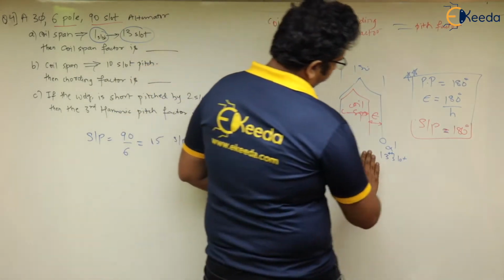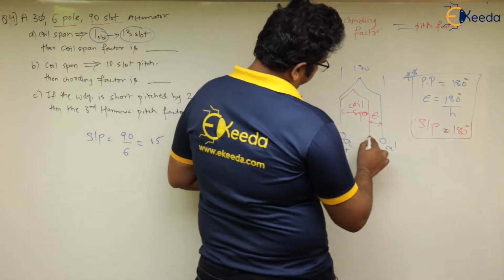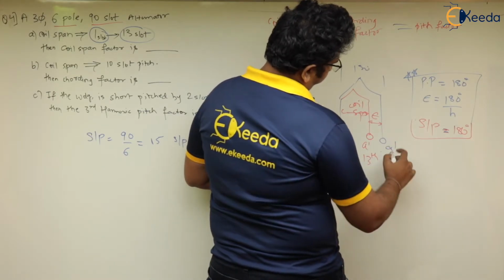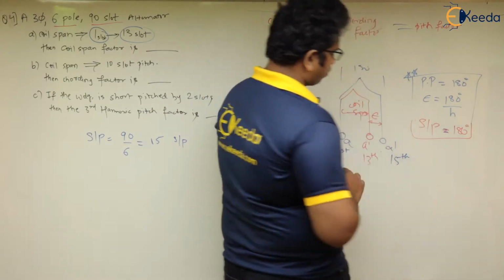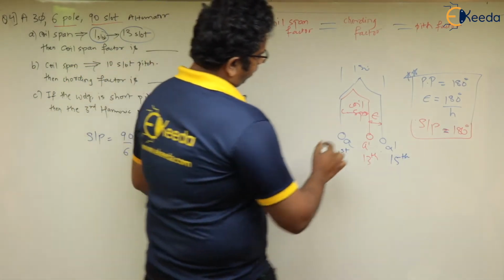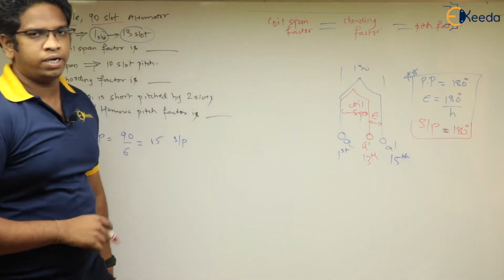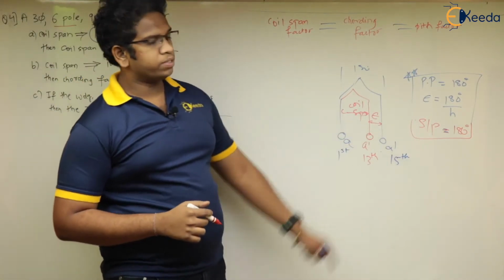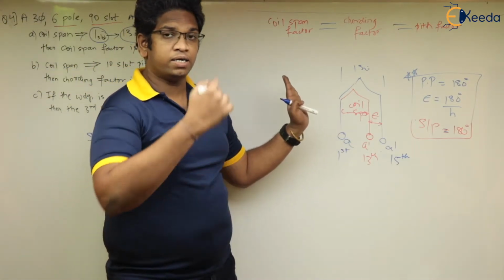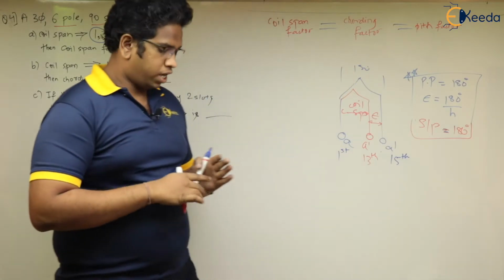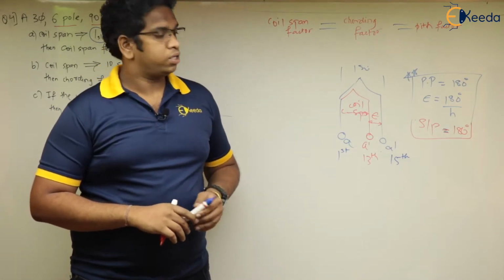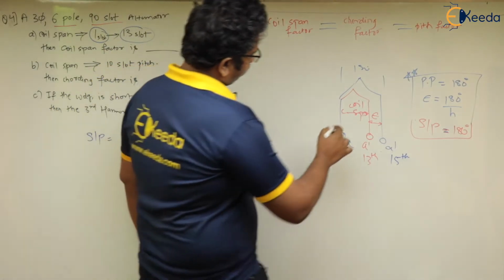Which means that this is not in the 15th slot. A dash is right now in the 13th slot, and our 15th slot is this one. Getting my point, right? Our 15th slot is this one. Now, what is the coil span here in terms of slots? In terms of slots, how much is the span? First is gone and the other one is on 13th, which means after the first, second, third, fourth, fifth, 12 slots will be there, because the difference is going to be 12 slots only.